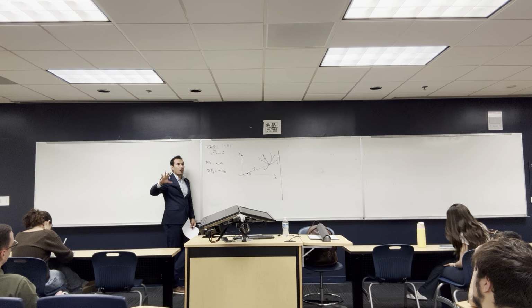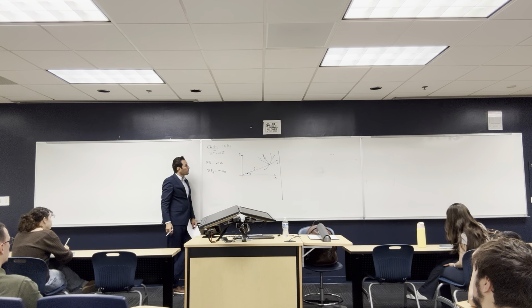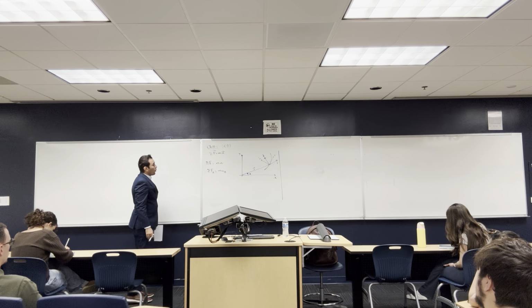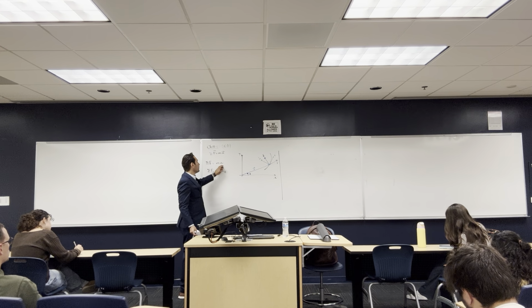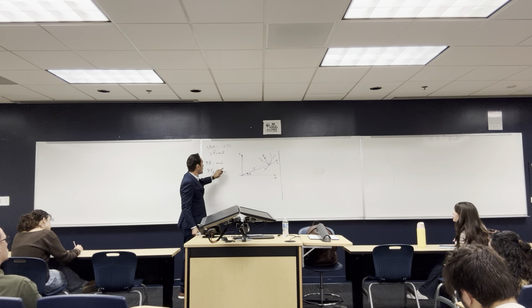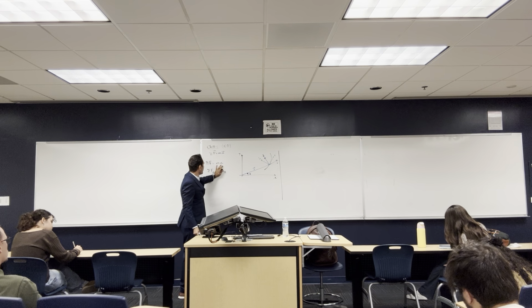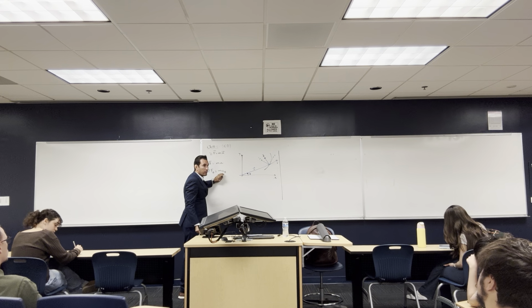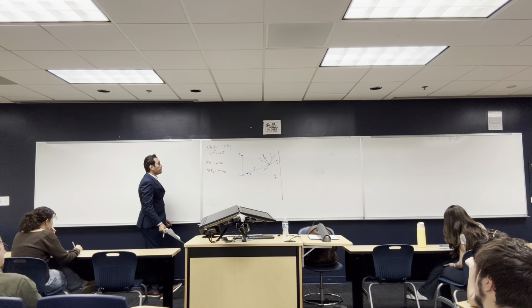It has a lot of r dot, theta double dot, same thing with a theta. So right now we know how to get the acceleration, and we call this the radial acceleration, and this is the angular acceleration. The theta one, that's very easy.